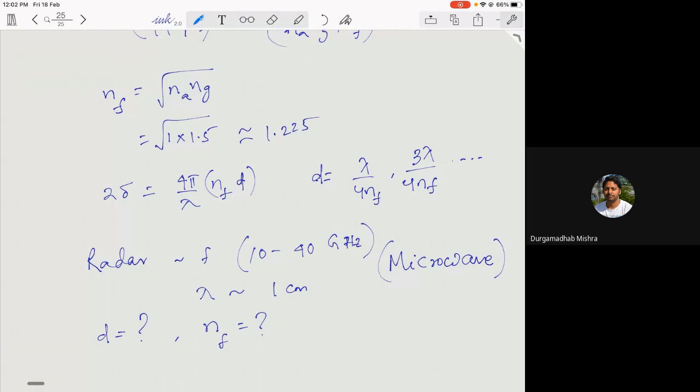So this is one extreme. Another extreme is you can actually increase the reflection as well. If you use exactly the opposite, you can increase D not by lambda by 4n_f, but by another additional lambda by 2, so you can create a constructive interference. Sometimes you use that in applications where you want to increase the reflection from a surface. So both extremes actually work using this concept. We will see maybe a couple of examples, and then move forward.